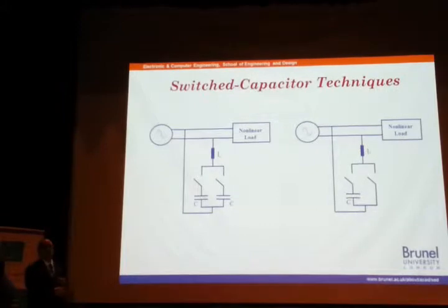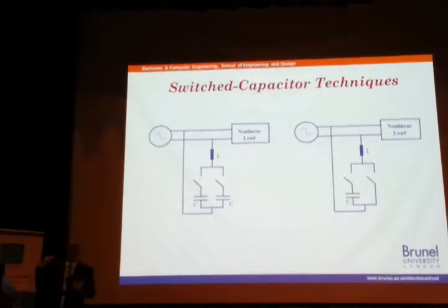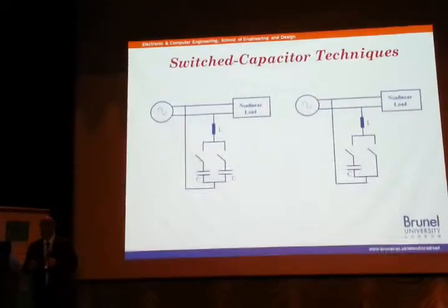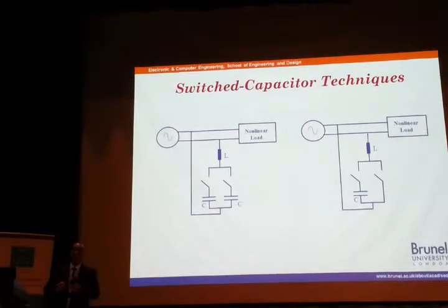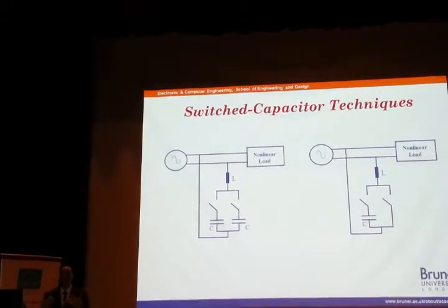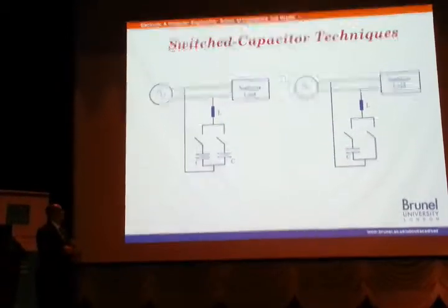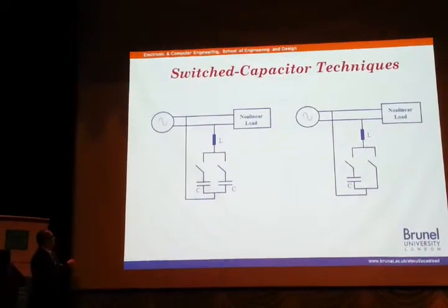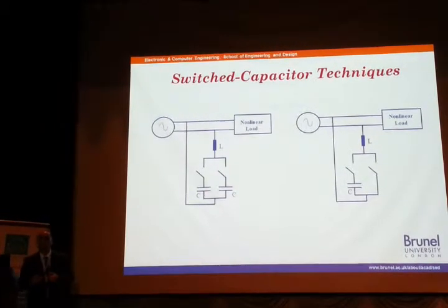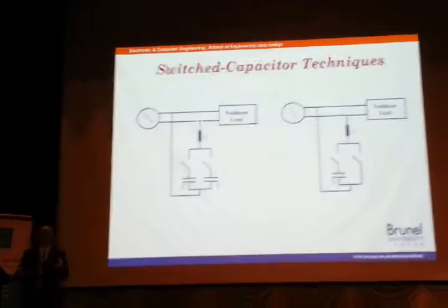And this is another, what we call the switched capacitor technique, okay? This is a new technique which has been developed at Brunel University, and we are well known within this area of active filters and renewable energy. Again, we have capacitors here, but these capacitors are AC capacitors, and the way we operate the switches, we release the energy from the capacitor to the main supply, okay? Either we have this configuration or that configuration, and it is well used now within the industry, especially in France, within the UPS systems.